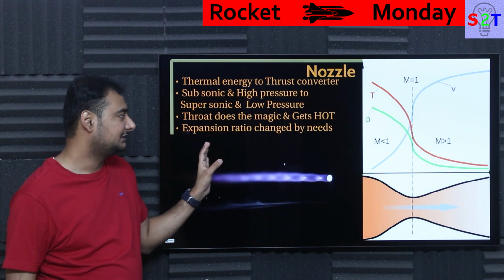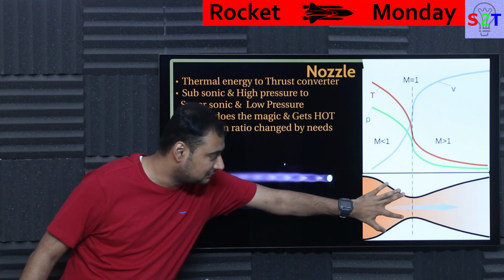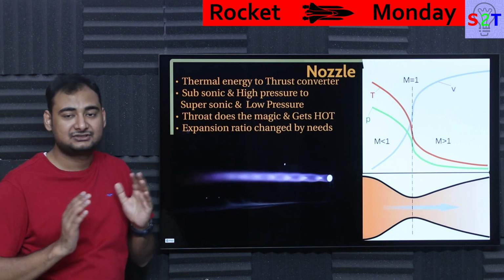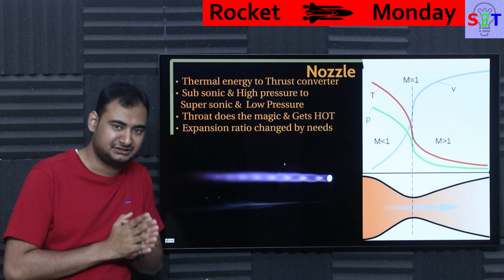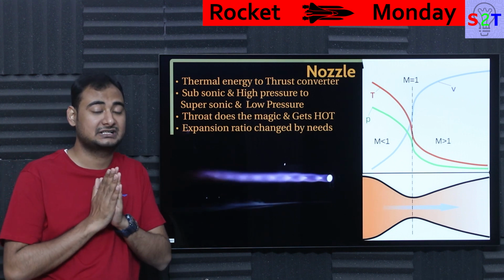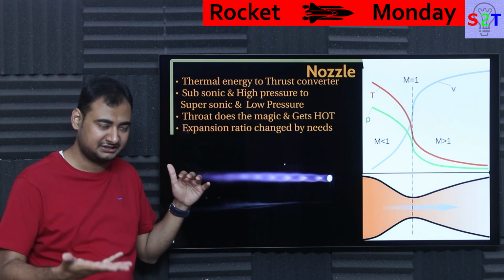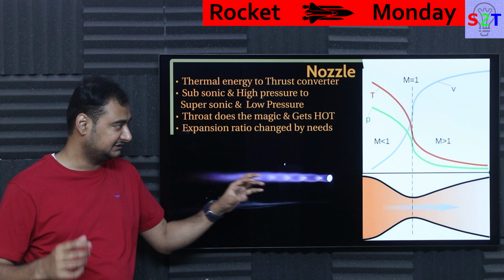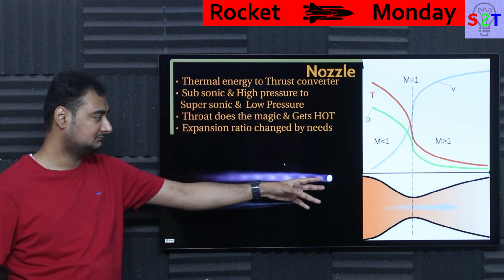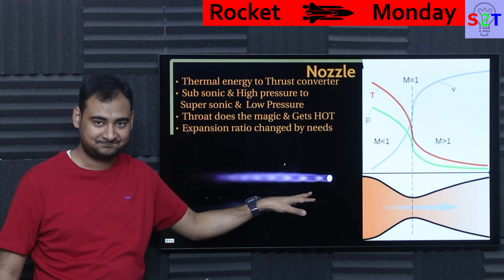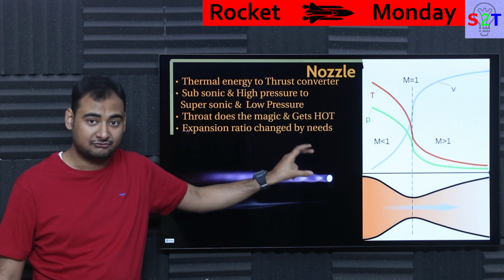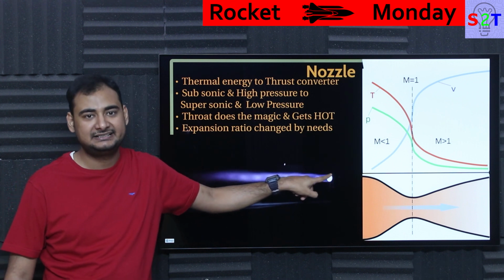And then you have to worry about what we call the expansion ratio, basically this throat to exit expansion. Now this has to be designed based on needs, what your engine needs to do. For example, if your engine is supposed to work as a stage 1 and it's not supposed to go to absolute raw vacuum, it has to start at sea level, so this ratio won't be too high. The reason for that is the atmosphere is there. In the same way the atmosphere can compress it here, worst case scenario, it can compress it inside the nozzle.